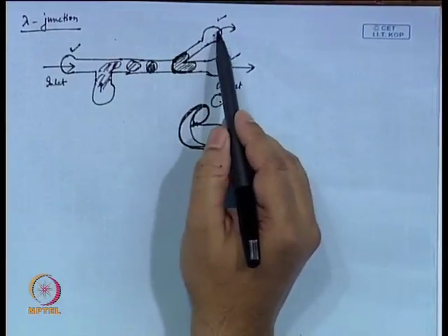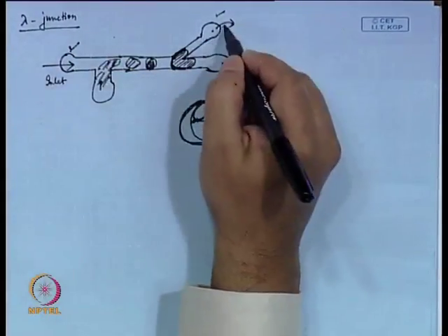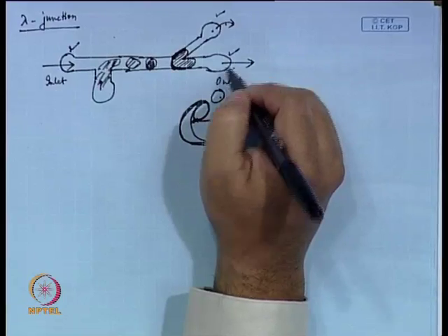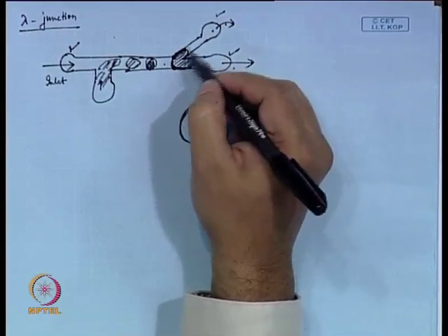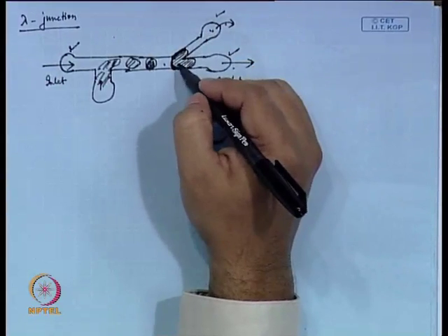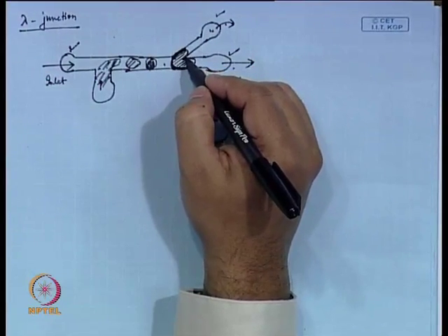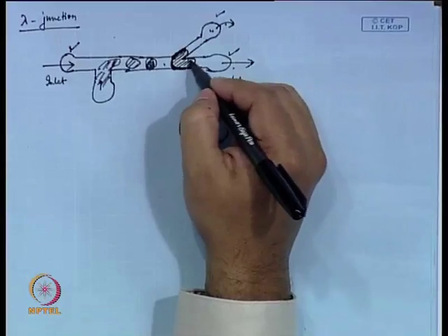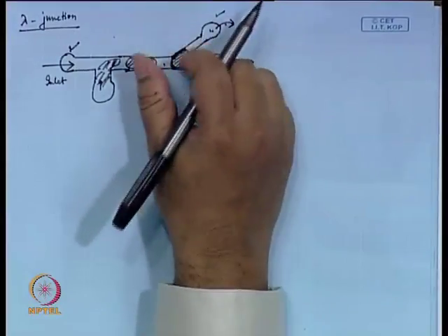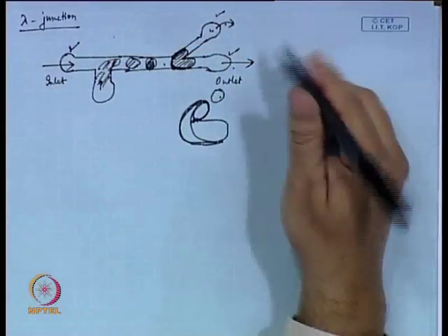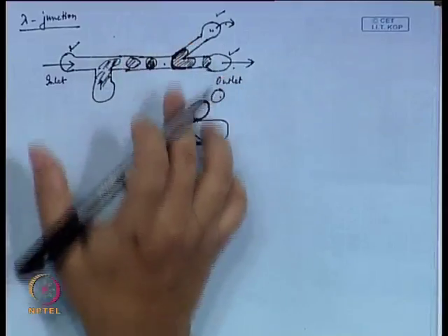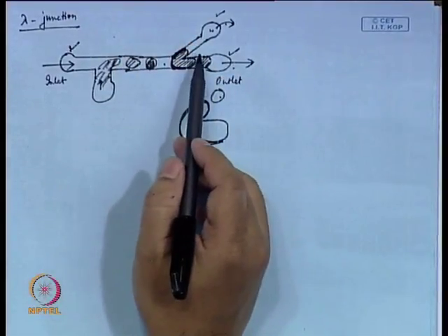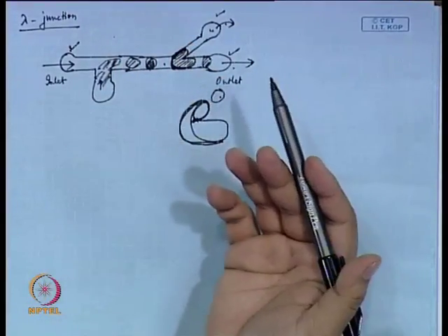On the other hand, if you have a pressure here, you have a pressure here, and you have a pressure here. So, if the pressure differential between this point and this point is not sufficient, then what will happen is it will go in a little bit, but it is not gone in sufficiently. So, it will retract and again proceed just like a droplet, and again this would be forming like a droplet. So, depending on how you play these three pressures, you can be forming daughter droplet or not. I mean, that is your will.